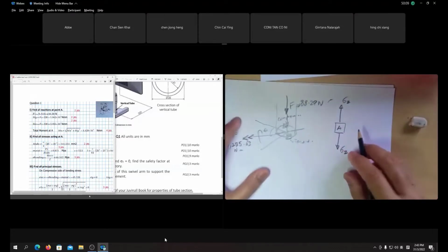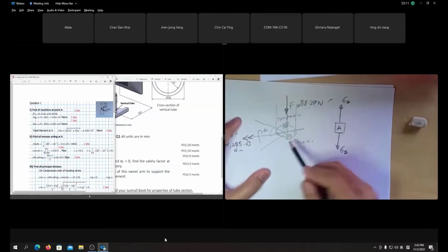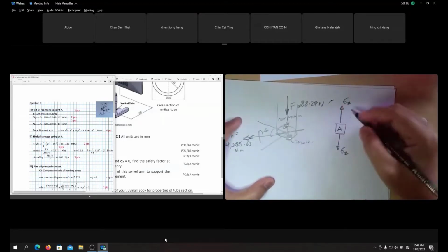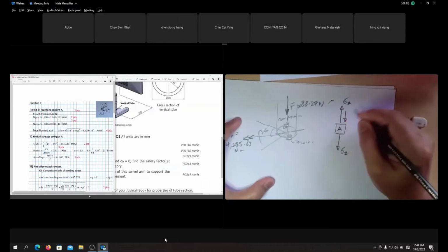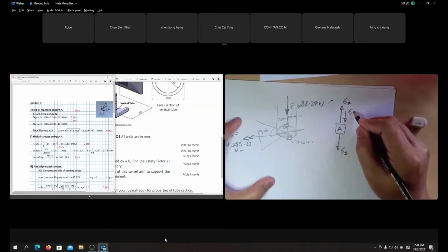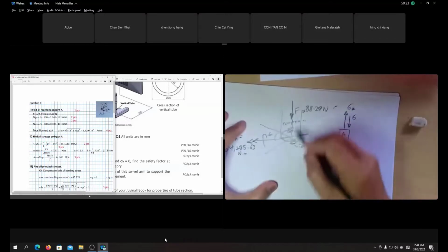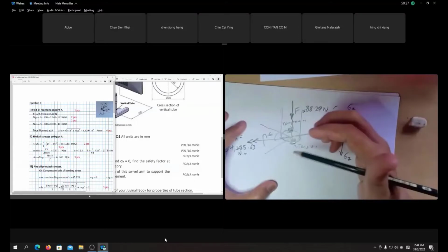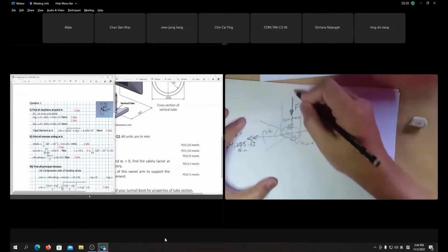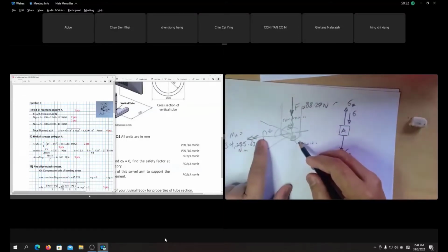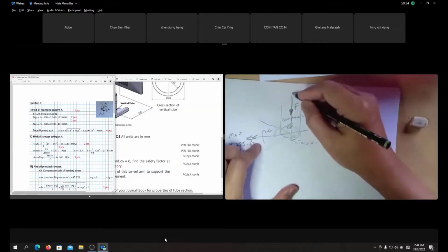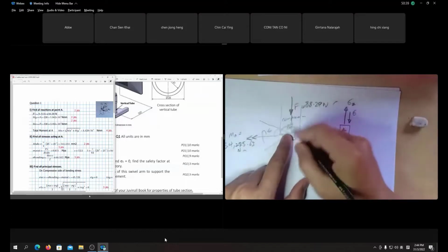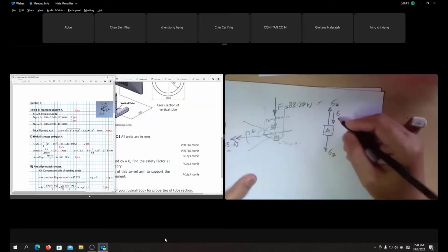We have a vertical force downward. Now we have sigma Z because of the bending, if we go for the tension side, but plus that we have sigma Z because of what? What is this force causing at element A? The vertical force. The reaction at A, we have vertical. I'm talking about the upper portion of it, guys, so you're not confused. Downward, right? Just now it was bending. And also plus we have direct force. The reaction at A, we have downward. In the upper portion, we have a downward force because of the weight of the knee. So we have plus another one.